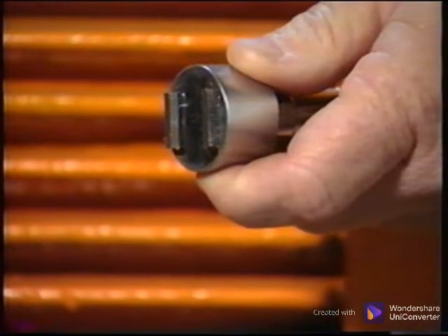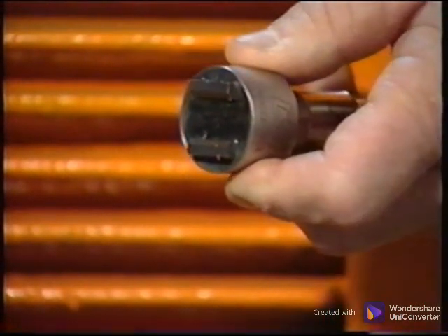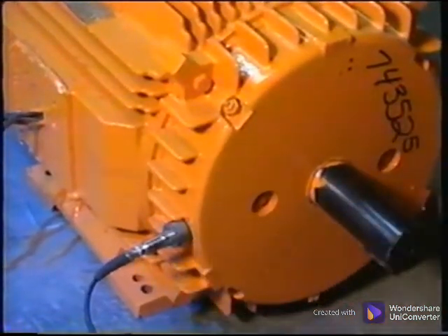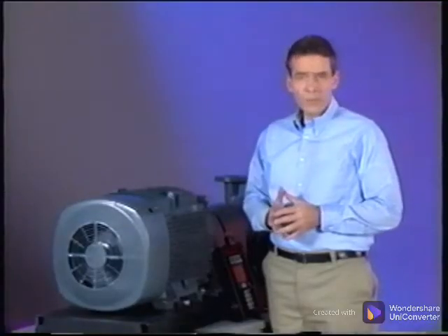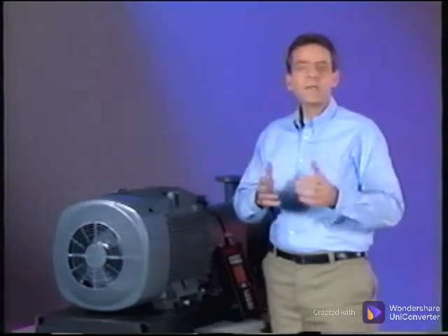It could be placed across the fins or in line with them if the magnet's two poles will line up. Although the horizontal measurement could be made on either side and provide good information, it is best to maintain the same horizontal measurement orientation from one routine survey to the next. The analysis equipment is so precise that even minute differences from one side to the other can significantly alter the data.